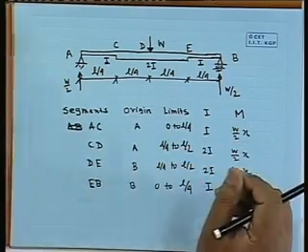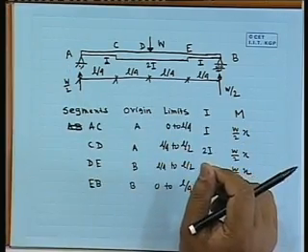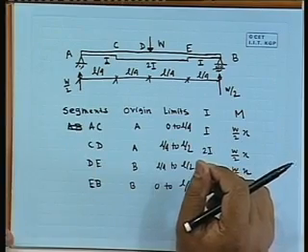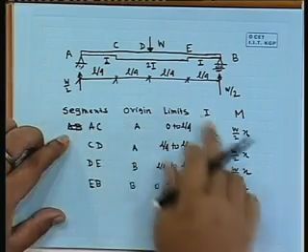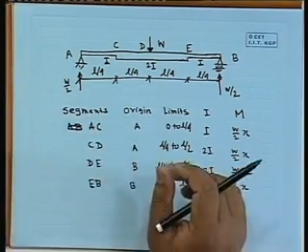So, if we are interested in finding out only one deformation, we can just put the expression of small m here. But normally in a problem it will be required to find the slope here, the deflection here, in many cases. So, there will be a separate table for small m. There you need not write the origin and all those, because that part is common.